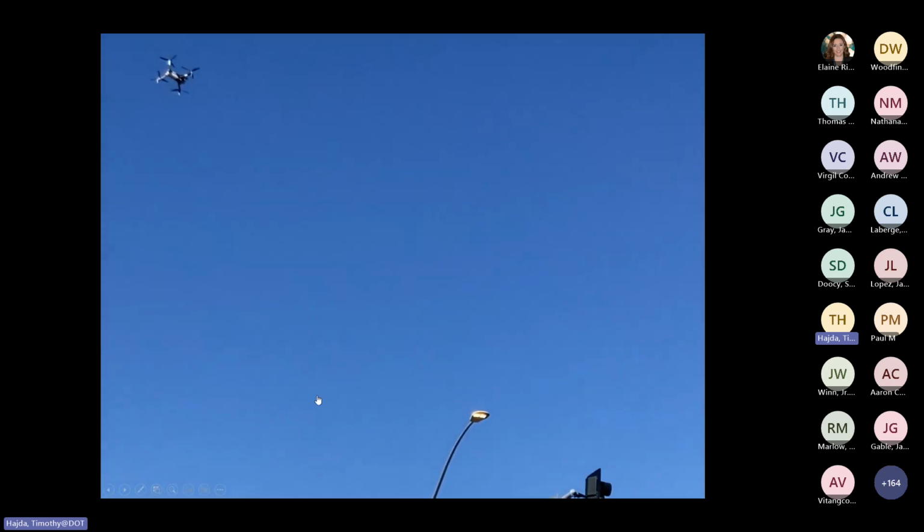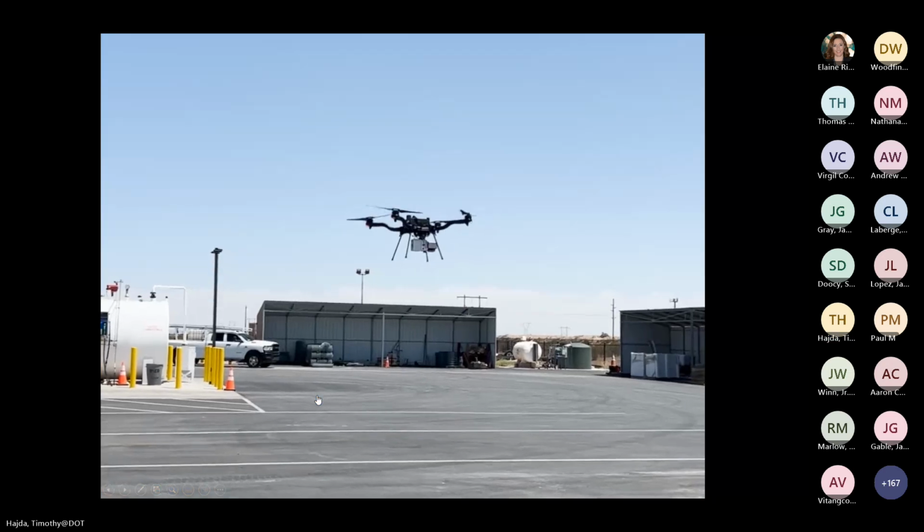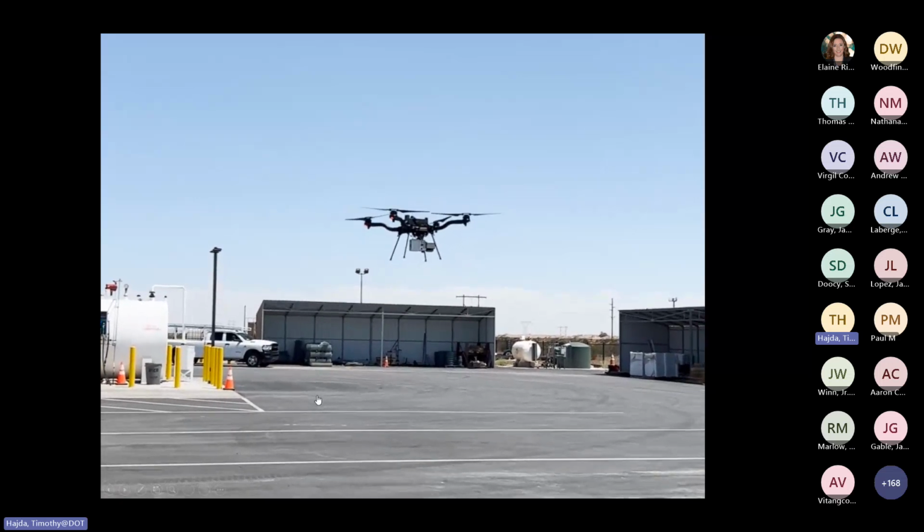So we continue to test other new drone platforms and payloads. Here's the Skydio X10, which Aaron kindly demoed for us here. It uses 6 4K 200-degree cameras to capture photographs, and also utilizes AI to fly autonomously and avoid obstacles. And again, this is the Phoenix Recon A LiDAR sensor on the FreeFly Astro drone. This LiDAR payload scans at 240,000 points per second and has the ability to capture multiple LiDAR returns. The multiple return capabilities allow us to filter vegetation from the point cloud to produce a bare digital terrain model.